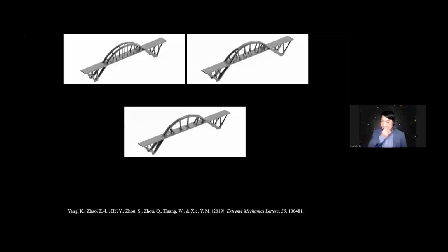The three bridges look quite different, but if you compare their structure performance, you will notice that the overall stiffness only differs by 3%. So in terms of structure performance, they're equally good, but we have multiple shapes to offer to your clients for them to choose from, or to satisfy other non-structural requirements or restrictions. So this is how we can obtain different designs by penalizing the existing shapes.